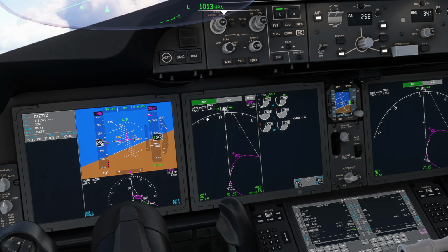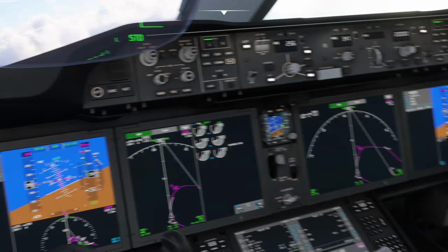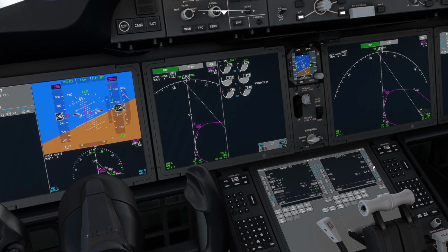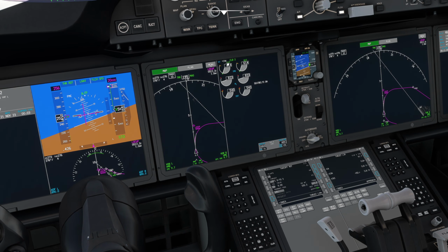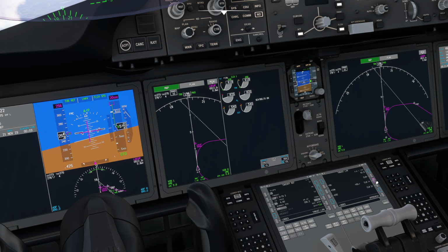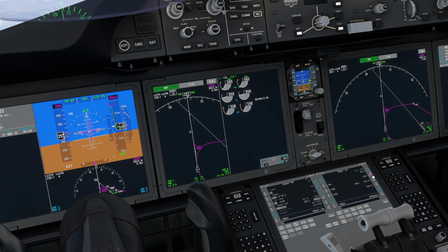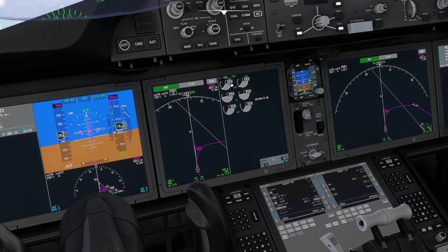But let's say we want to get there a bit quicker. Let's set standard as we're going up to a flight level. Yeah, we want to get there a bit quicker. Well, what we can do is actually select climb 1, and you'll see that 61.7 is the current climb 2 power. Select climb 1, and you get 69. And if we still want more thrust, we can select climb, and it goes to 72.7.